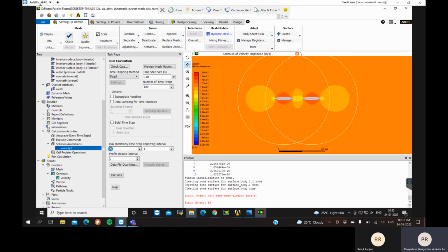You can increase it later, Dada, and I will leave these things as 20 and 1 and 1, just to see the mesh motion and velocity, whether they are under control or any vorticity is forming, as we saw in previous simulations. After you finalize your mesh, you can use the same settings and ensure a good time step and sufficient sub iterations. The reporting interval and update interval are not a big matter, you can use 20 or whatever. These can be left as default.